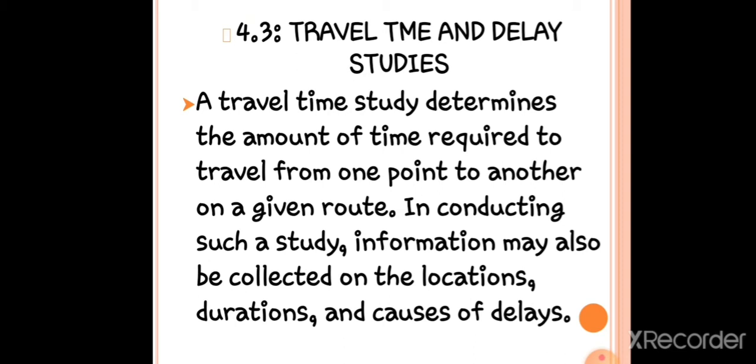So our topic is travel time and delay studies. By the way, what is travel time and delay studies? A travel time study determines the amount of time required to travel from one point to another on a given route. In conducting such a study, information may also be collected on the locations, durations, and causes of delays. When this is done, the study is known as travel time and delay study.